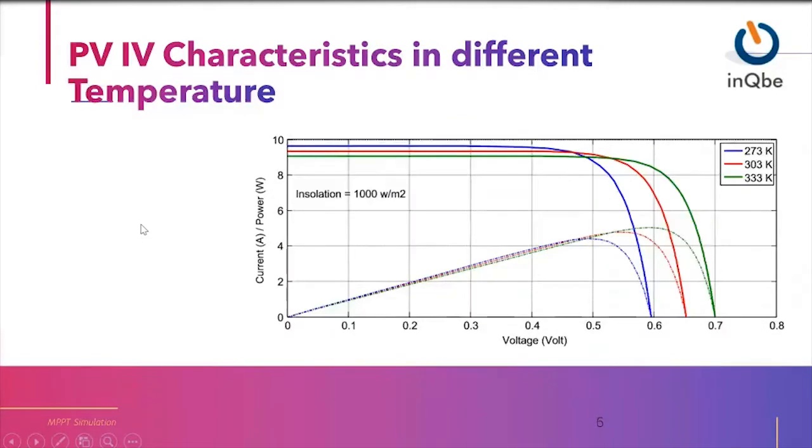Then I will show another picture, of a temperature difference. Suppose irradiance is the same and temperature is varying. The voltage per cell will vary, and according to the variation, we should vary the load. That means when there is a variation in temperature or irradiance, we should vary the load. I think you all got the basics of the MPPT method, that means variation of load.